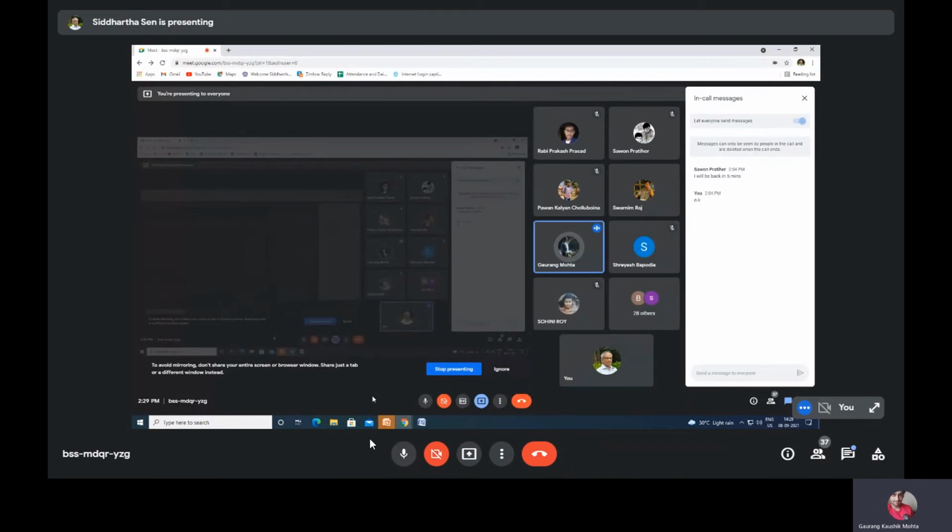Sir, in the previous experiment number 2, you said that output should be between 4 milliampere to 20 milliampere. So we need to have any range in that, or the minimum should be 4 and maximum should be 20? Yeah, minimum should be 4, maximum should be 20. Okay. But here it is not that part, we have left it. It is only 0 to 2.5 volt DC for the sake of simplicity.